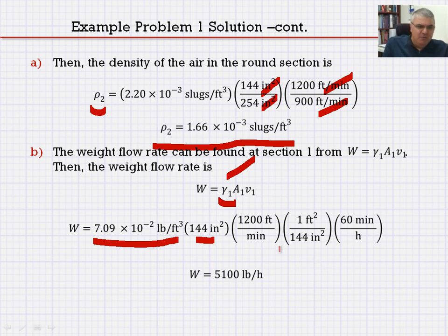One must be very careful with the unit conversion here. Remember that we want to calculate pounds per hour. As such, anywhere we see a minute, we need to convert that to hour. That conversion is done here, minutes per hour, and this is multiplied here by 60. So eventually we're going to have the h here, the one that I highlighted in red.